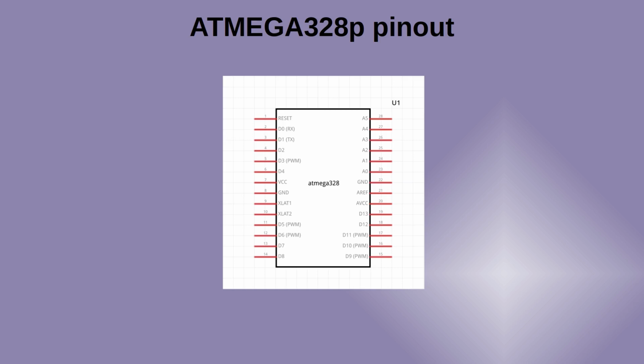I'm also wanting to use this with the Raspberry Pi Pico and perhaps other microcontrollers, so that I can use those peripherals without needing to create my own custom PCB board. The same advantage of I2C applies for any microcontroller, as it uses fewer pins compared with SPI.